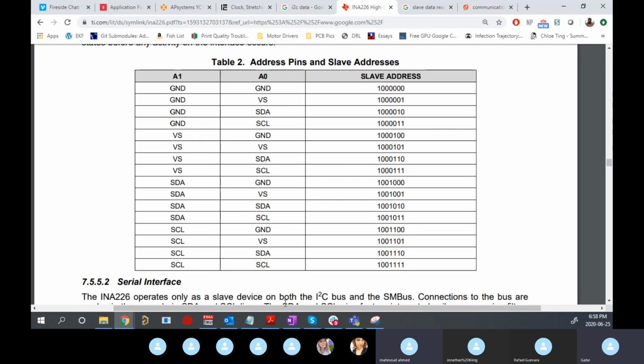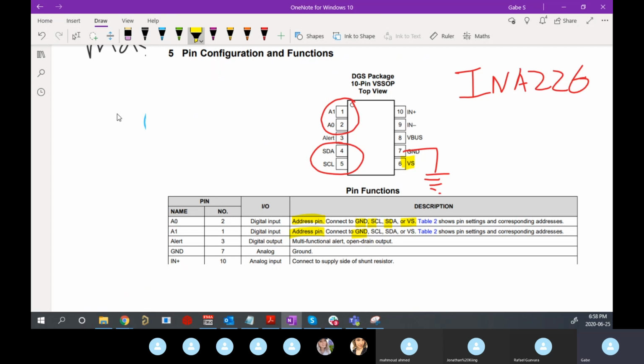I think that's how the BMS slaves work, actually. You set their address through software, and then you can talk to each individually. Yeah, that's a great point, because those are using UART, right? So they don't have this built-in slave address. And so TI had to create that software to add another layer of addressing for you. Because it did it for you, it's super nice and easy now. But without having done that initially, you have to do that extra work.